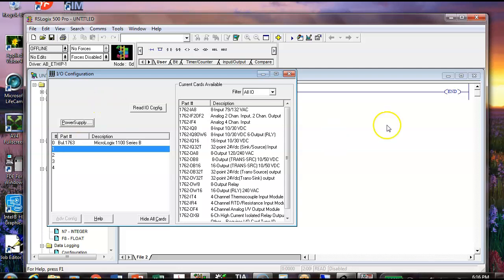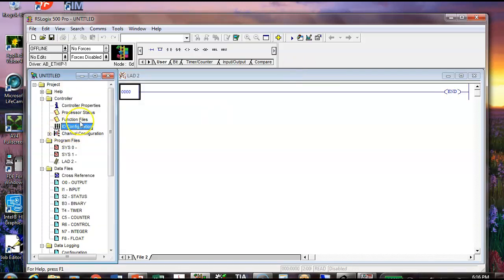Of course, we've got a lot of them. We hadn't put any modules on them yet. We do have some Siemens that I'll bring over here and show you all those when I give you a little hint of how that works. So the first thing we do is select the CPU. The next thing we would do, if we have additional modules, if we have that rack over there, then what we need to do is come over here and pull these little covers off of here.